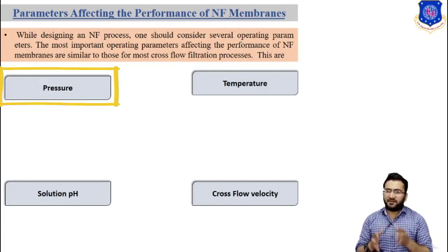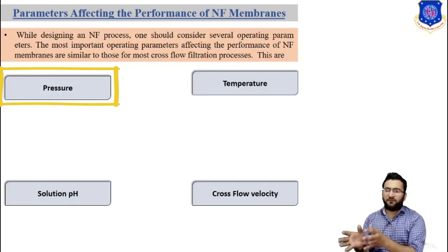Pressure difference is the driving force responsible for nanofiltration. The effective driving pressure is the applied hydraulic pressure less the osmotic pressure applied on the membrane by the solute. Nanofiltration provides good separation at a net pressure range of 150 psi, or we can say 10 bar or higher. If we increase the pressure, we will get higher flux in the nanofiltration process.